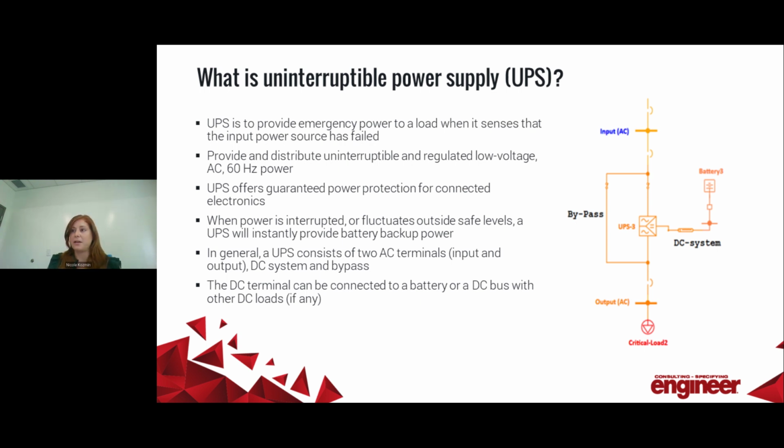I'm not going to go into many details about how the inverter works, but I'll describe it briefly because I think it's really cool. It's a solid state device and it mimics an AC current and voltage utilizing a DC power source. So it uses insulated gate bipolar transistors, IGBTs, acting as static on-off switches to reverse the connections between a set of input and output waveforms.